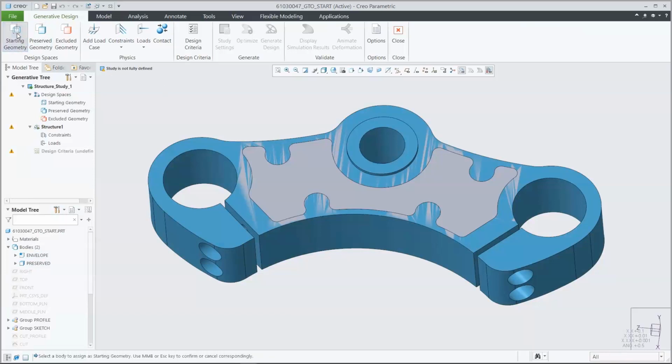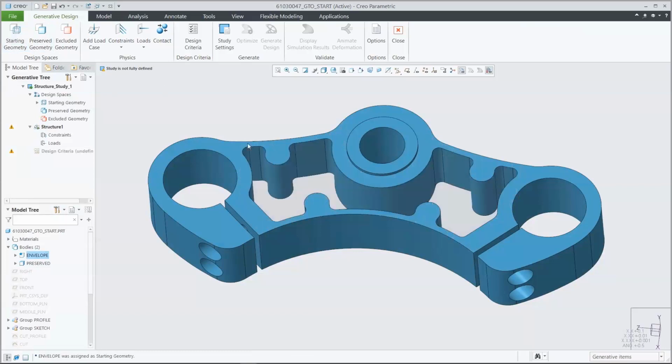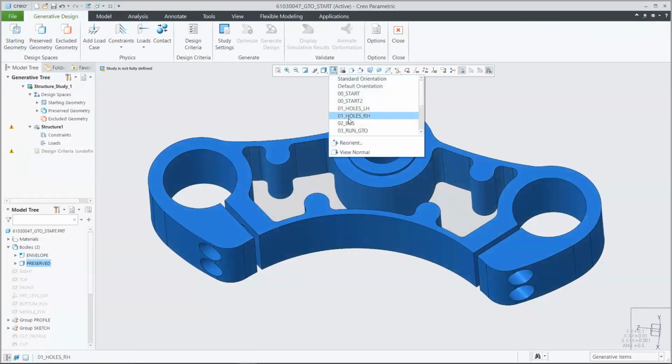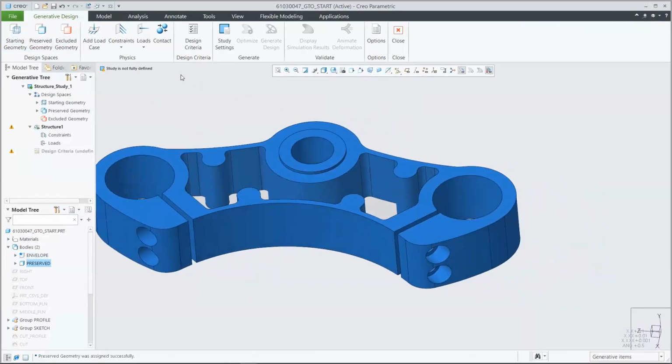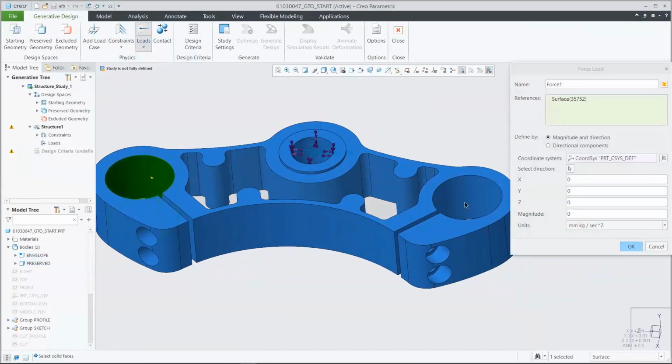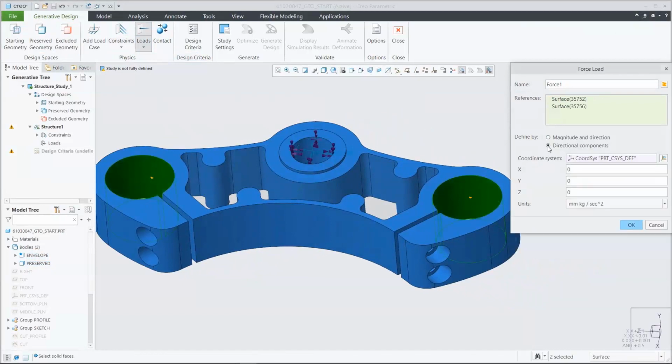First things first, we'll go ahead and lay out some physics. And you could lay out, first and foremost, some constraints with this to say where the part's going to be held down. Right, so we can go ahead and get that defined here. It'll be right there in the pin in the middle. And then from there, we could say what types of loading conditions that we have. Be forces, moments, centrifugal forces, things of that nature. Get this all laid out here, and change around the values, change the units for whatever you need there.